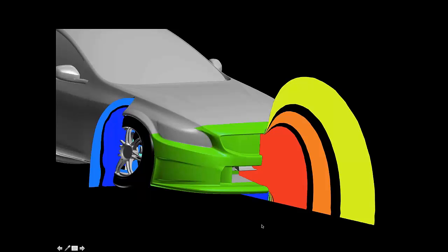So here's a pressure contour graph of what you're looking at on the car there. So you can see in the red that big high pressure stagnant air bubble on the front, and your splitter, you'll see if you can increase that splitter length out the front there, you'll just keep capturing that air. Generally there is a limit to it. If you can't balance it out with a rear wing, you will find you're too front biased on the car there. And then underneath you can see the blue region where the flow's accelerated and you've got the low pressure building up, and on the outside of the wheel you can see that low pressure built up from the cheek throwing air around the car there.